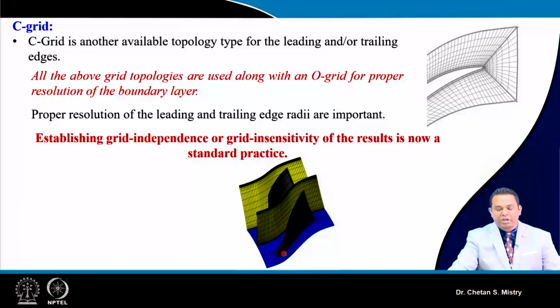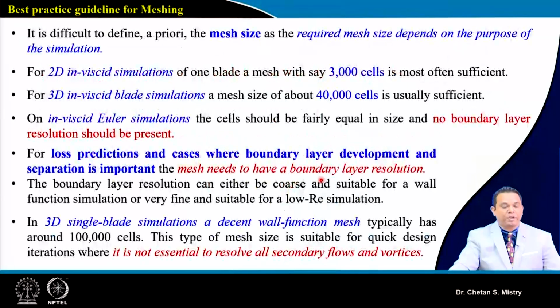So here, if you look carefully, this is representing the blades, and here you can see we have systematic gridding near our hub surface. In the same way, this is representing what is happening along the span. This is a passage block, and near the tip region is of our interest. In order to capture the tip leakage flow, we are looking for such kind of elements, and this is representing the periodic surface.